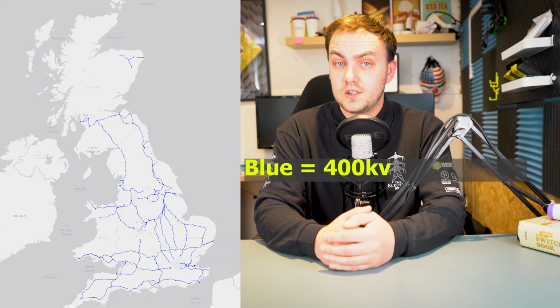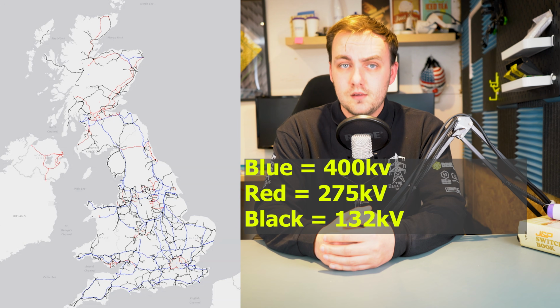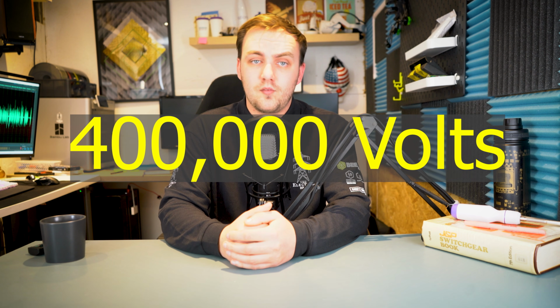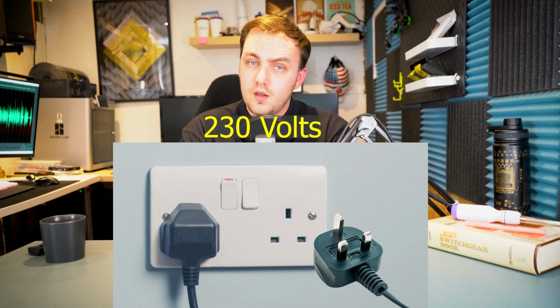When people talk about the grid, they usually refer to voltage levels. In the UK, these are generally 11, 33, 66, 132, 275 and 400 kV. That K means 1000, so 400,000 volts, compared to the 230 volts in our homes. Voltage is something we control with transformers. Increasing the voltage lowers the current for the same amount of power, and that's a big deal.